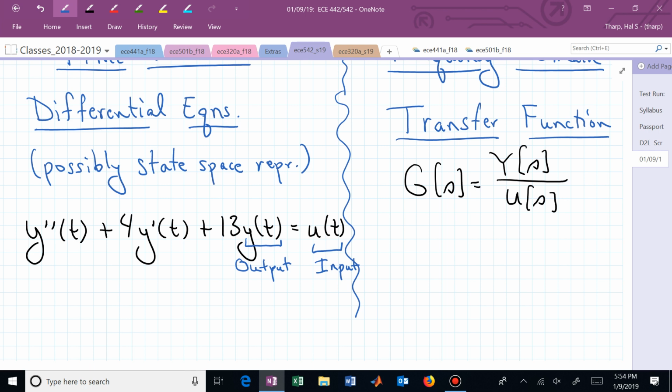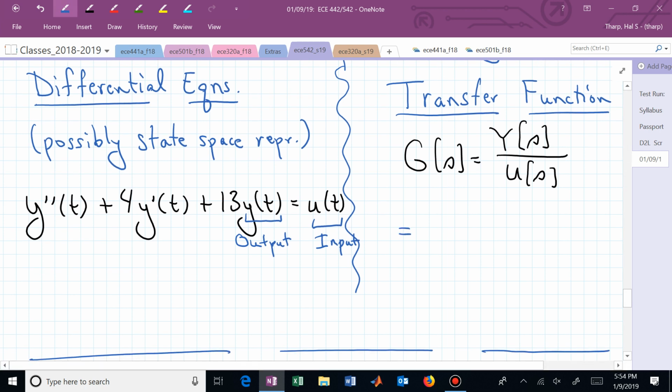It now governs the behavior of our system, and that's in the pole locations, which are downstairs in the transfer function. In this particular case you could Laplace transform both sides of that second order differential equation. Since we're interested in a transfer function, we don't have to worry about initial conditions. We can neglect those, and that's the hard part of recalling the Laplace transform of a derivative. Now it's easy because we don't have to worry about how those initial conditions collect when we have higher order derivatives than first. If I now Laplace transform a second derivative, what does that correspond to in the frequency domain?